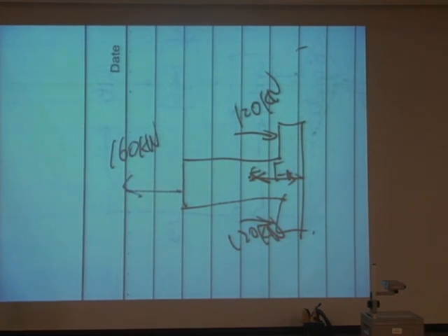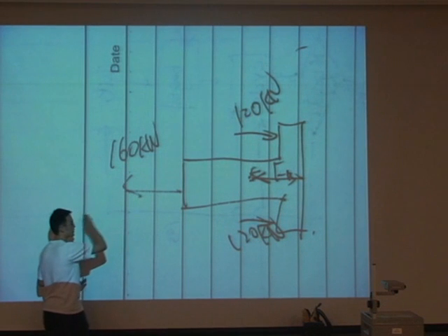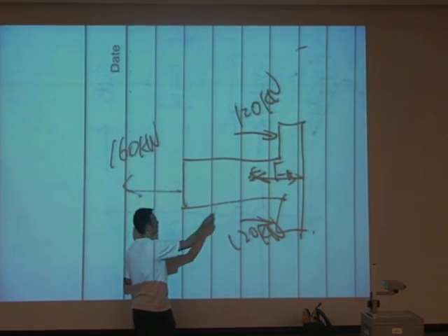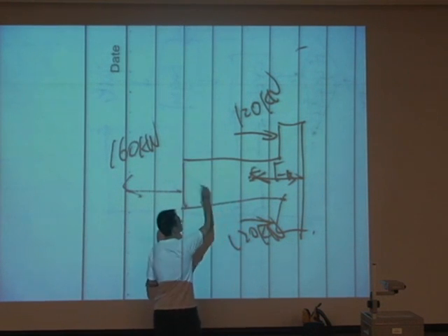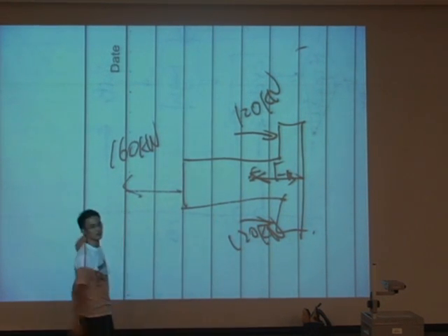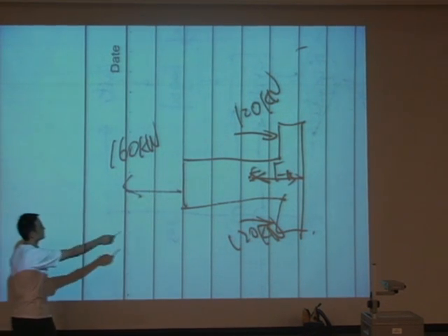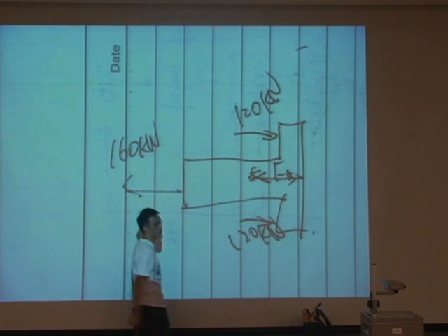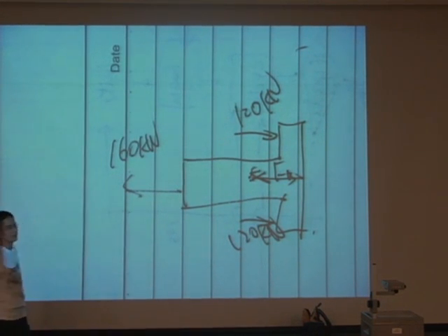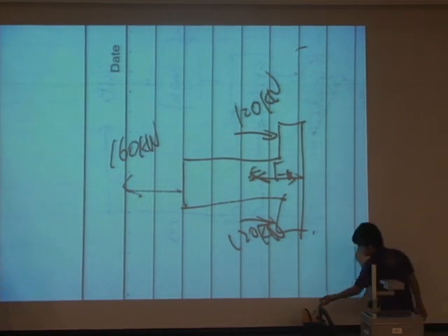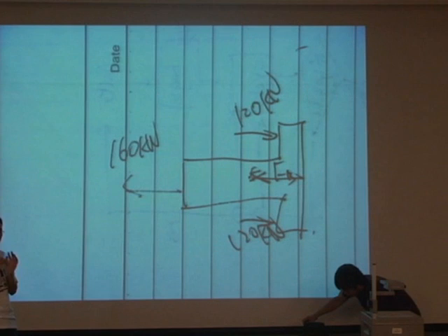So how do we know this FB? Again, we link back to static equilibrium. The resultant force should equal 0. So the horizontal force at this side plus the horizontal force at this side equals the summation of these two horizontal forces. So 160 plus this FB equals 240. So you know what the FB is here. But the question is, what is the force experienced inside this member? What is the force experienced by it? Any idea?